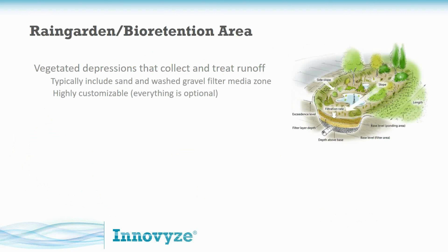So plants are super important. They're going to control that sediment and not let that sediment wash away. You can also stabilize that soil with fabrics and whatnot. So that's maybe a common practice, to have plants and fabrics. But the plants also, their root systems are going to be absorbing nutrients and allowing infiltration to occur better and better.